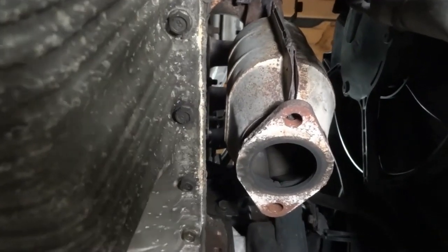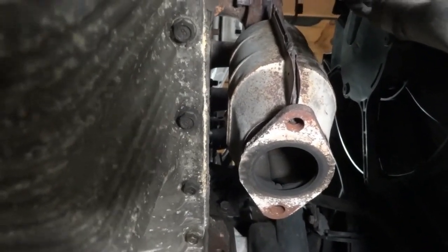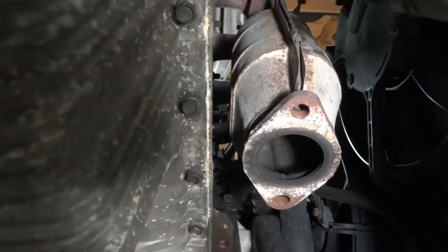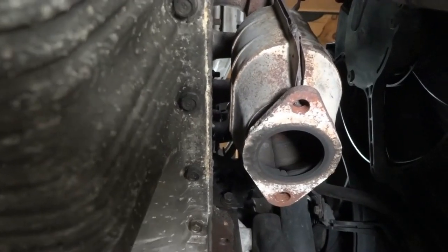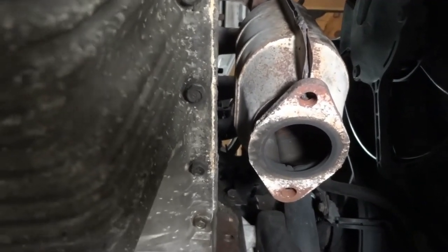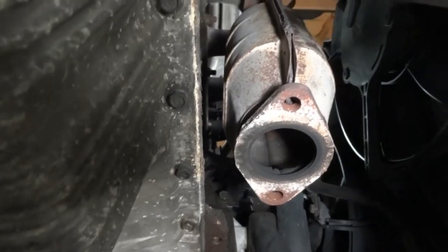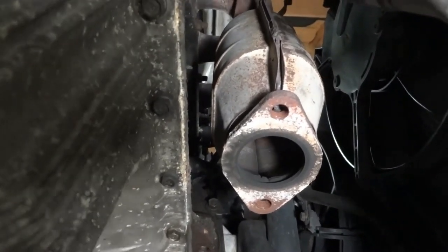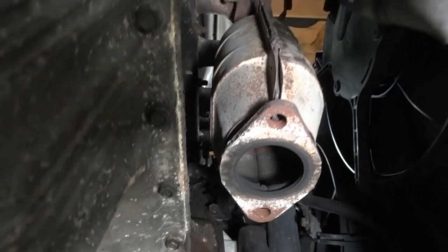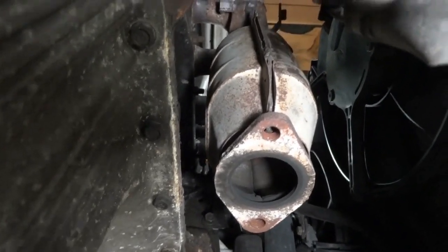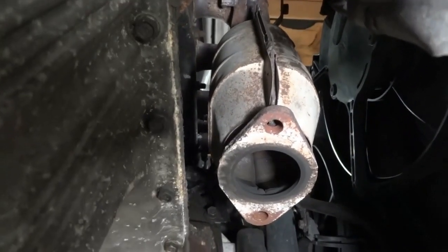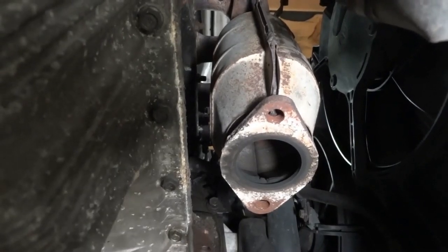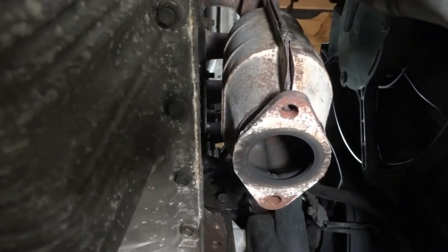Now, after replacing the catalytic converter and the downpipe, we have to look at our fuel trim numbers and make sure the engine is running right. We have to double check that the engine is not running rich or lean, because we gotta find out why this catalytic converter went bad. Okay, so I will get these catalytic converters, this one up here and the downpipe. I'm gonna replace them, and then I'll bring you guys back up so we can verify our repair.